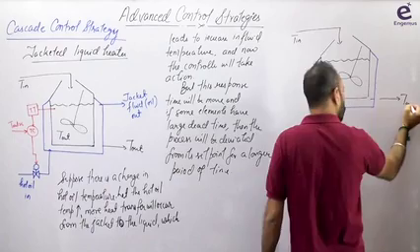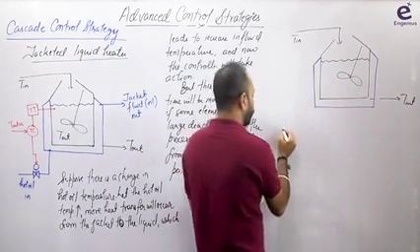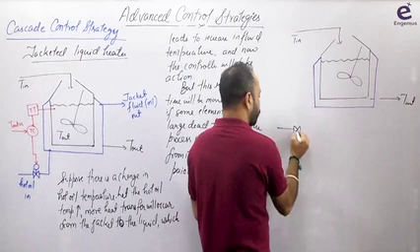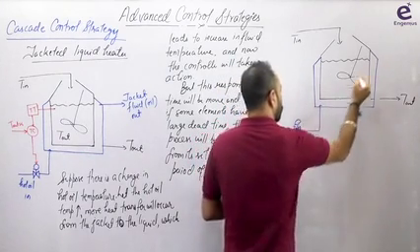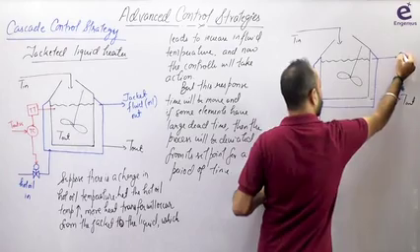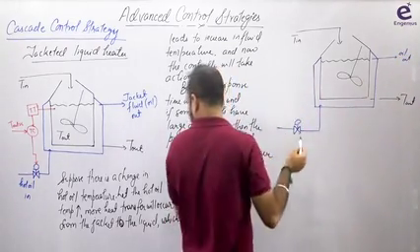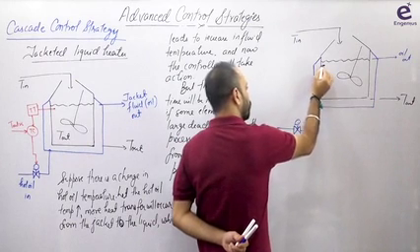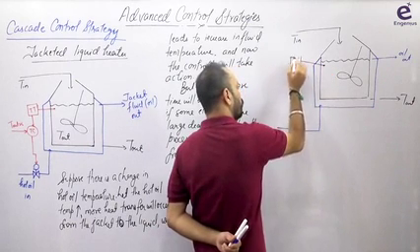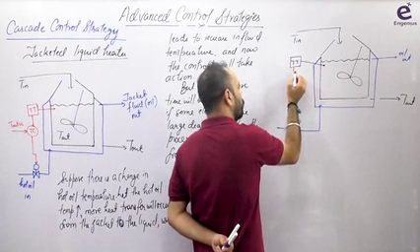This is T out. We want to control T out. Fine. Hot oil was coming from here. Exactly the same. Everything is the same. See how we are going to change the things. And then this is oil out. This was the problem. Now everything is the same. I'm taking one measurement here. This is the one measurement which was earlier also going to the transmitter and then it goes to the controller.